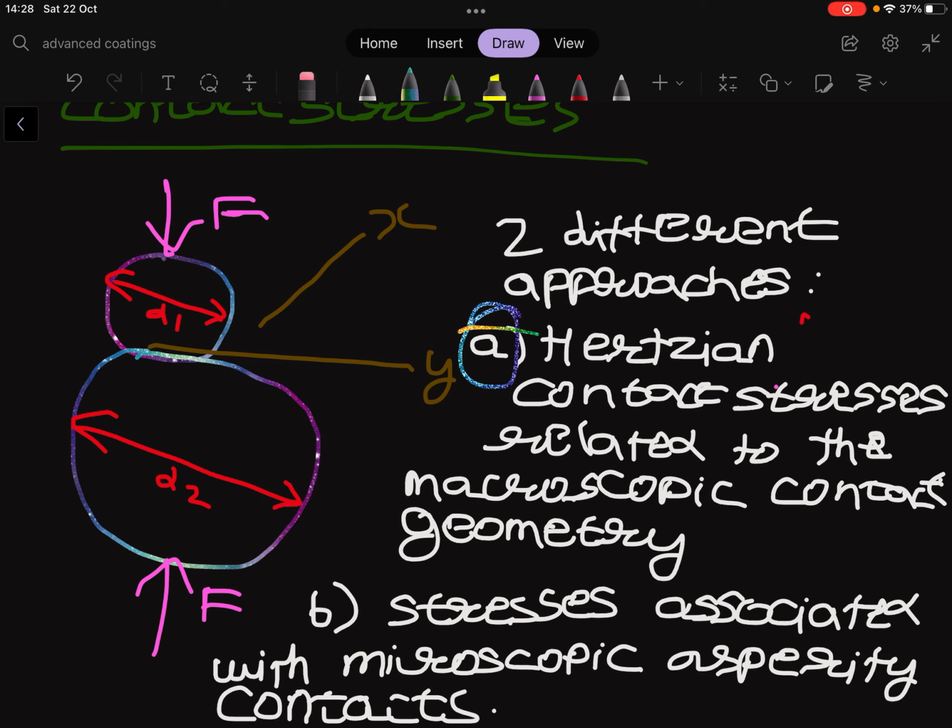When these asperities come in contact, we have a real stress transmission, and originally the contact area is very small. But in geometry like in this figure, we have high local pressure, so these small asperities are easily flattened to generate a real smooth surface.